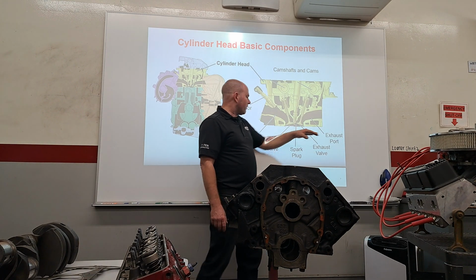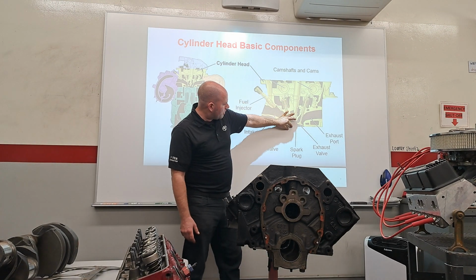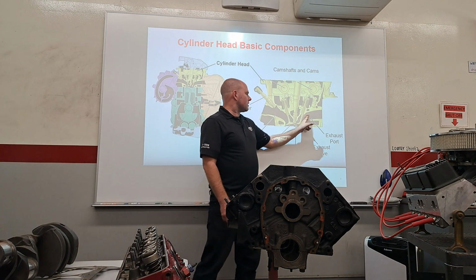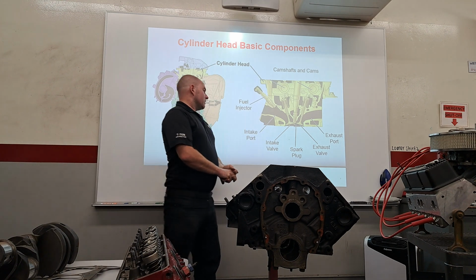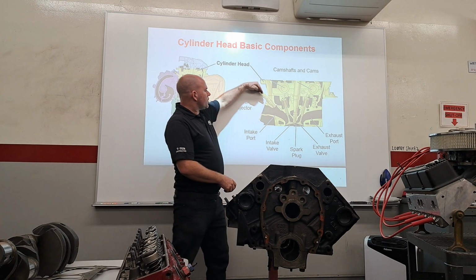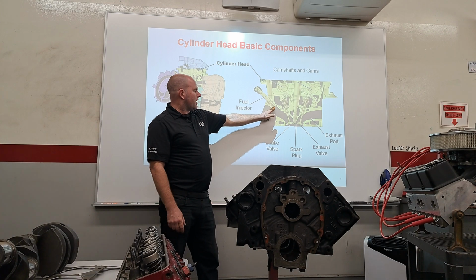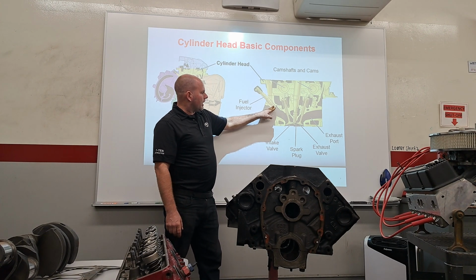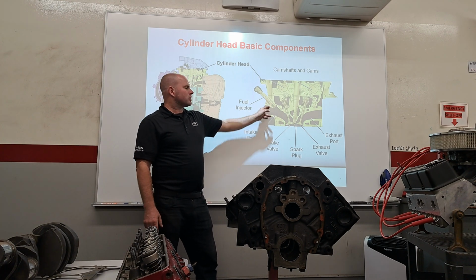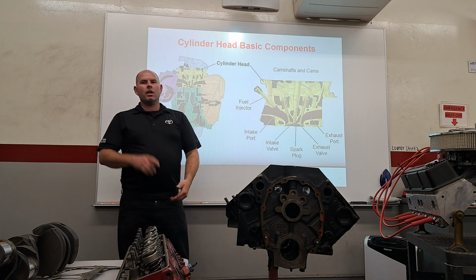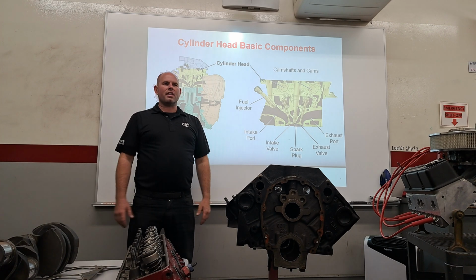Right. So if you look at these, this is the port that goes to the cylinder. This is the port that goes from the cylinder. Kind of make sense? Now let's go into a little more detail. We've got an injector right here. Look at where this injector is. This injector is spraying, and the fuel is hitting the back of the valve. So what type of fuel injection system would you call that? Port fuel injection, exactly.